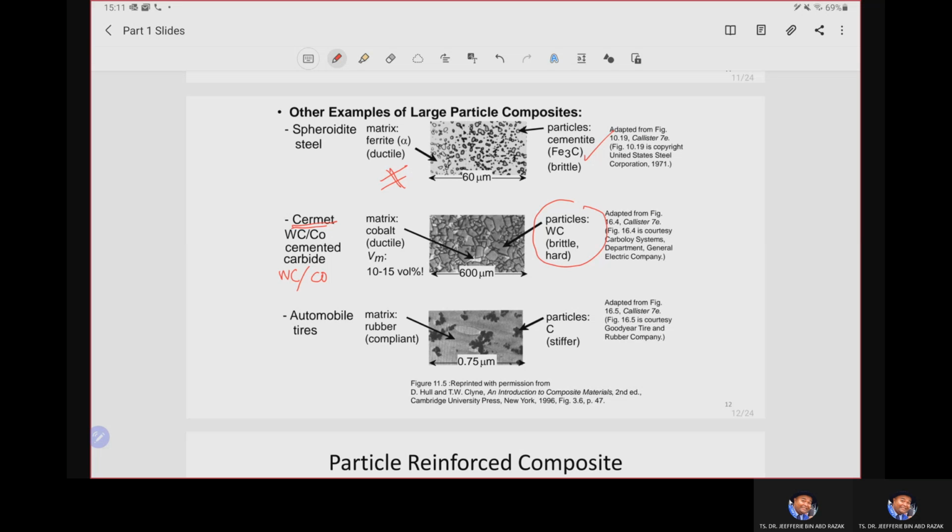All right. As you can see here, a large volume percent of the tungsten carbide particle is utilized, about 100 minus 10 to 15. Okay, say for example, we take 10, then about 90% is the reinforcement phase. Thus, maximum abrasive action can be obtained from this ceramic composite.